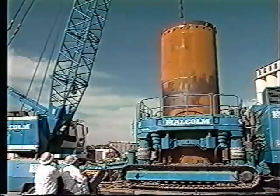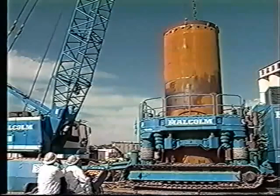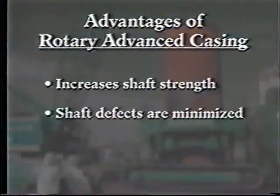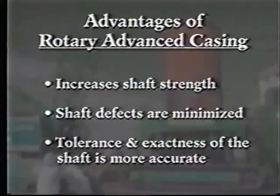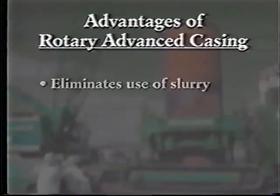Rotary advanced casing is a proven installation method that provides a wide variety of advantages. This method makes a stronger shaft. The risk of defects within the shaft is minimized. Tolerance and exactness of the shaft is more accurate. When horizontal loads have to be transferred, the production of a sound drilled shaft is essential.